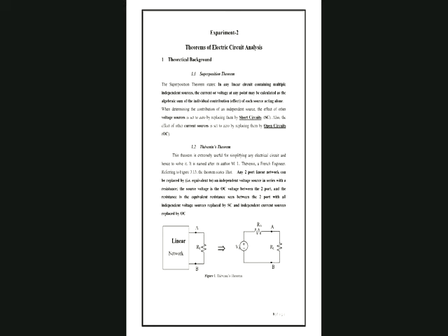It means that the voltage across or current through an element in a linear circuit is the algebraic sum of the voltages across or currents through that element due to each independent source acting alone. The superposition theorem determines the contribution of each independent source to the variable and then adds them up.